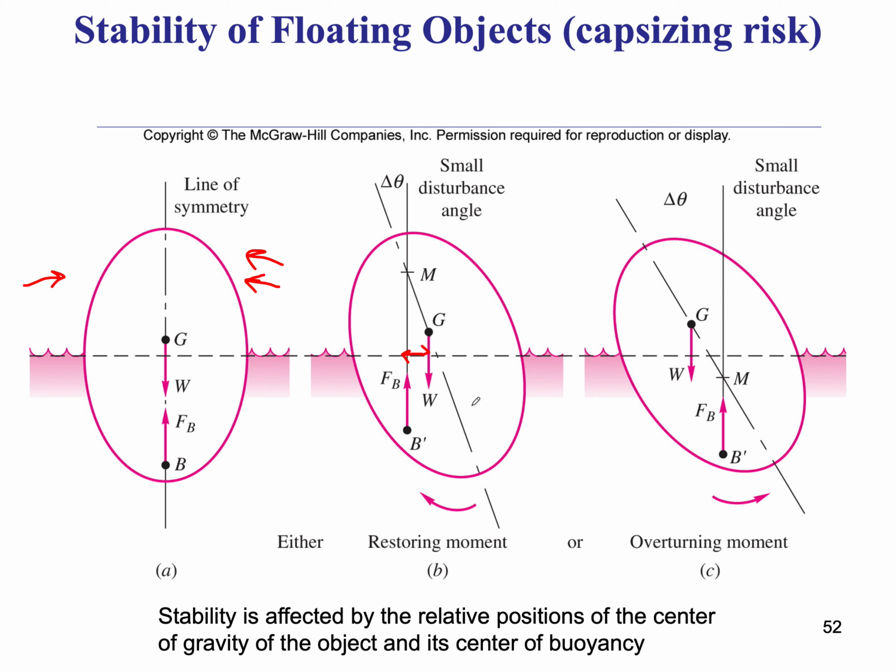You'll see it's creating a clockwise moment and it's trying to resist it. So we get a restoring moment in this case. This is a well-designed hydrodynamic stability system where a disturbance gets suppressed and the system goes back to its original location.